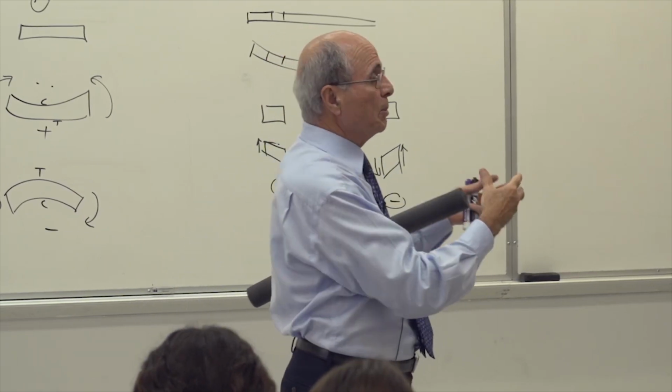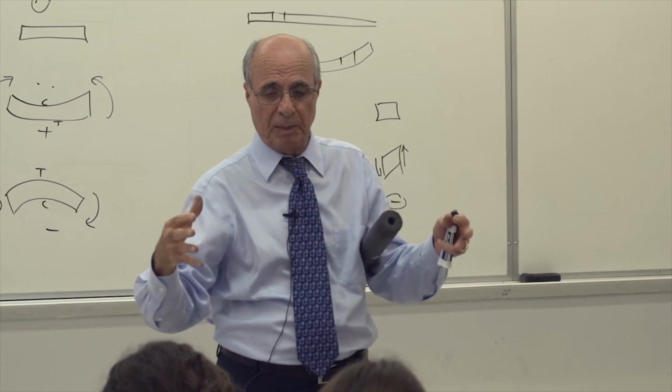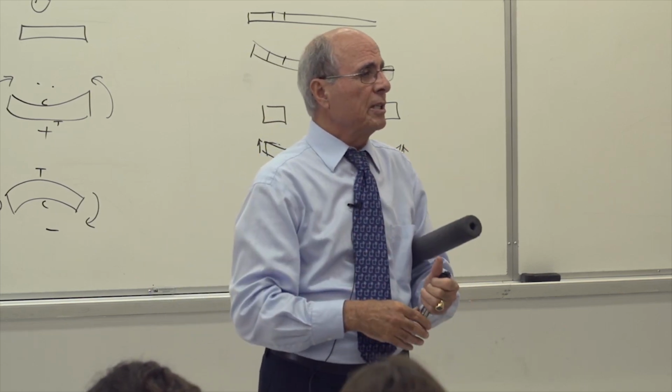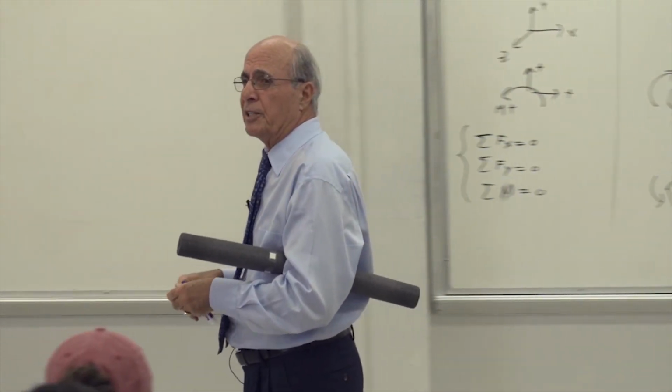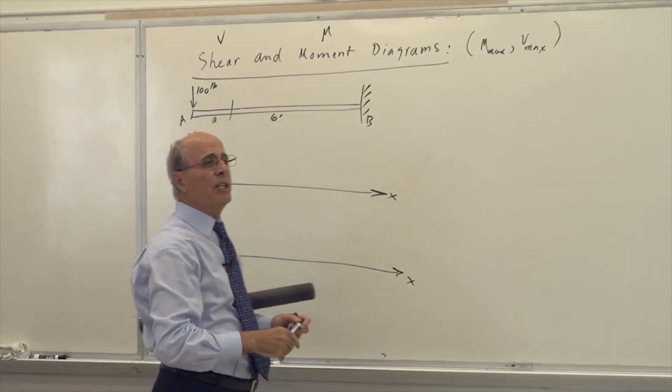When things become a little bit more complex, which I'm going to do when I do a larger beam on Thursday, I'm going to draw for you the free body diagram. But this is such a simple case, it does not require a free body diagram. If I make a cut here, this is down, the shear must be going up.